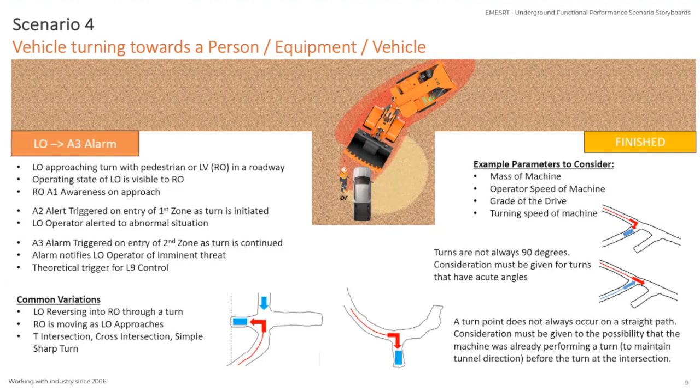And the opposite can occur too, which is the next image to the right, where we've got a gradual left turn before a full sharp right turn. And that's quite common, particularly on decline. So you might be driving down the decline in a corkscrew fashion, heading down the mine, and you might hear another vehicle coming up towards you. You need to do the opposite turn into a passing bay to allow that vehicle to pass you. So that's actually quite common, that particular example.